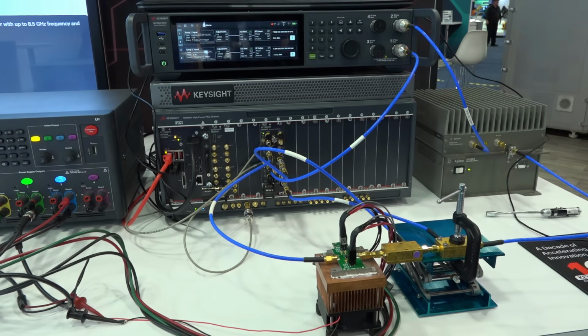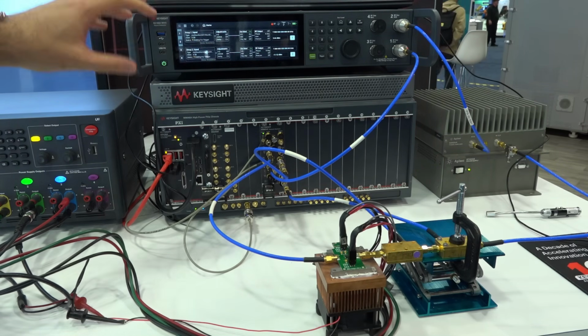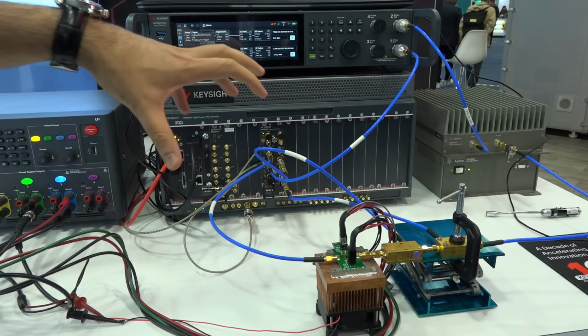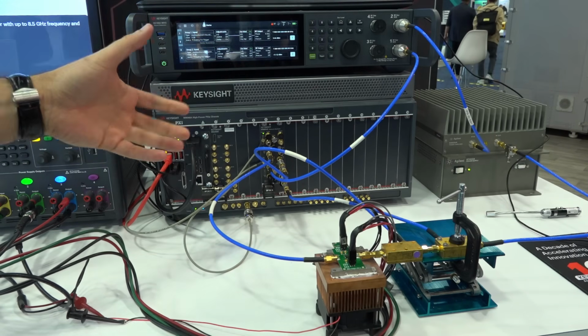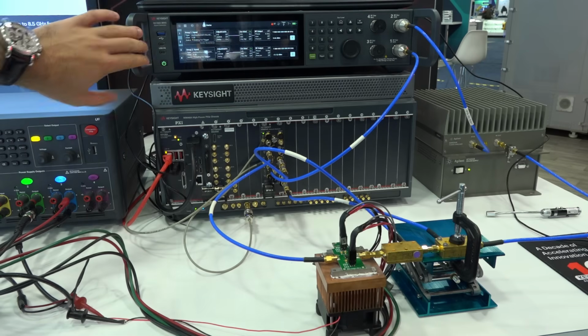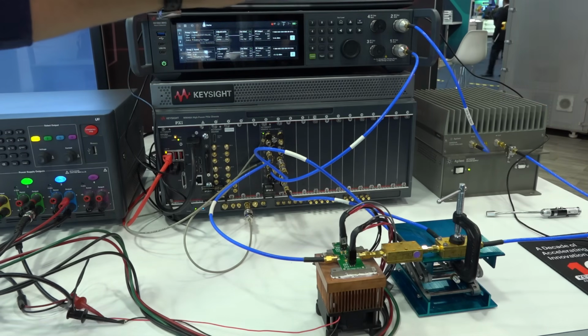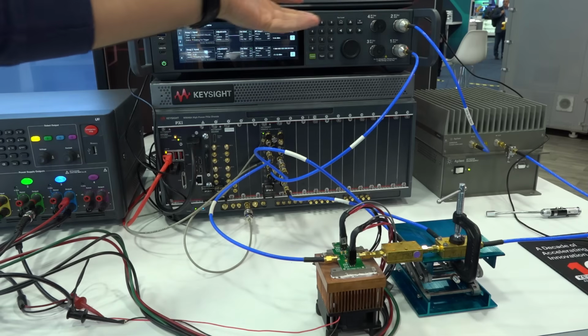So here at the Keysight booth, we're going to look at an active load pull system. Now we've talked about active load pulls in the past, and it's all about how you put the whole system together and combine it with the software to extract the parameters you want from your setup. So here we have the MXG, which is a 4-port instrument with 100 megahertz of analysis and computation bandwidth, so you can synthesize any waveform you want.